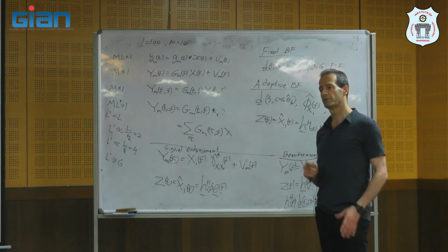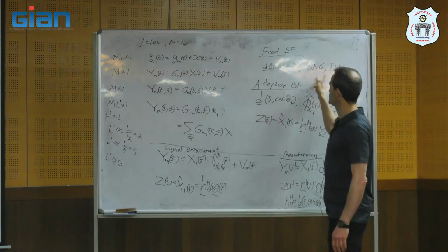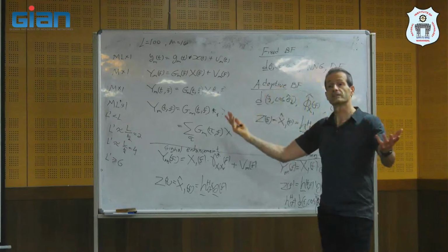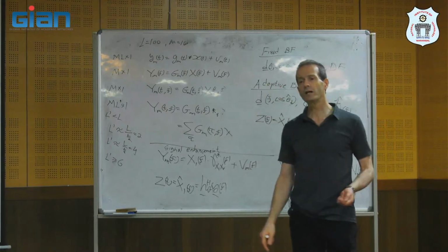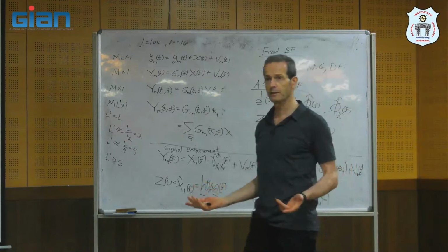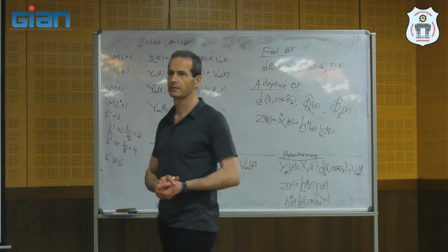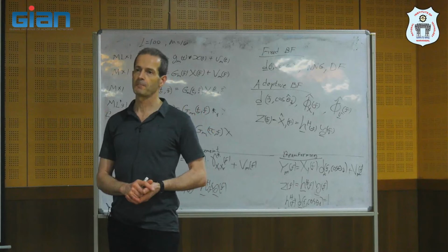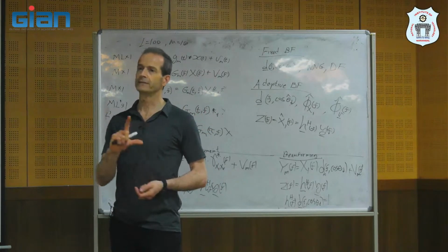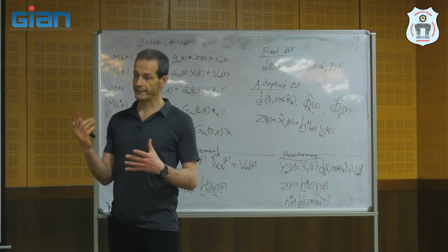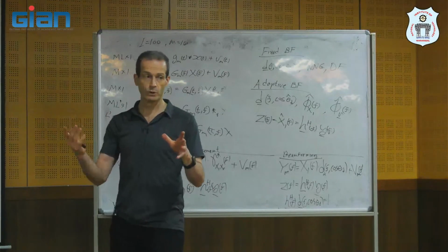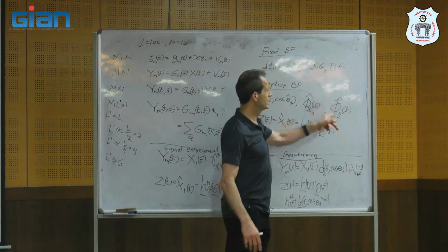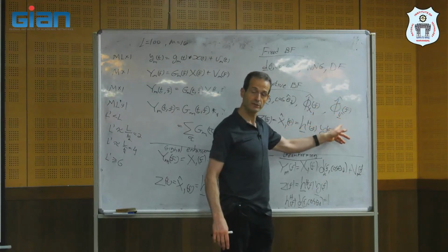But then, with a fixed beamformer, I need to assume a certain noise field. Maybe spatially white, maybe diffuse, maybe a combination. I don't know the spatial field of the noise. So do I want to add another algorithm to estimate the variance or the correlation matrix of the noise?